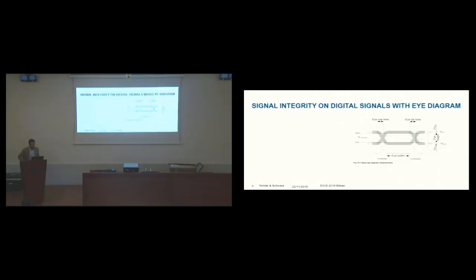So first of all, well, eye diagram, as you may know, when we deal with digital signals, digital interfaces, are very common and very useful, because we can assess rise times, fall times, signal to noise ratio, jitter performance, overshooting, ringing, many parameters that can be useful to get an idea on how our signal integrity is maintained.